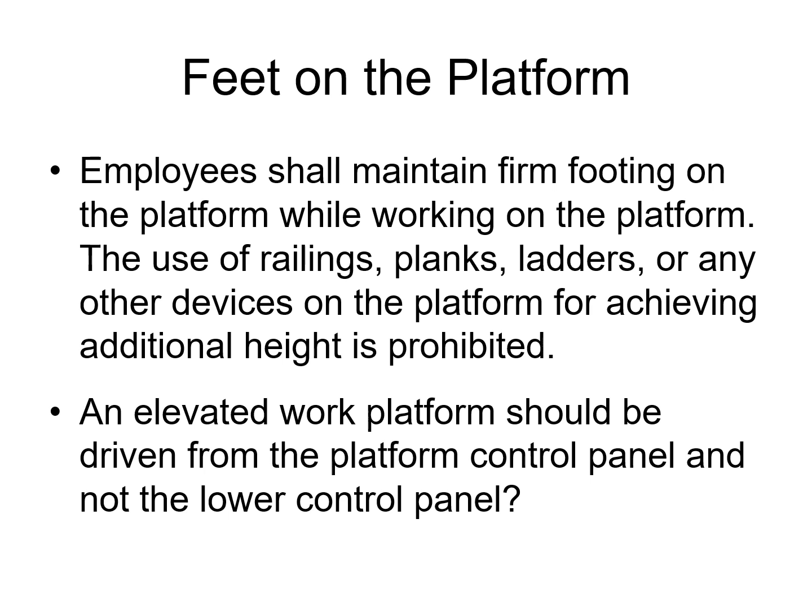Employees shall maintain firm footing on the platform while working on the platform. The use of railings, planks, ladders, or any other device on the platform for achieving additional height is prohibited. An elevating work platform should be driven from the platform control panel and not the lower controls.